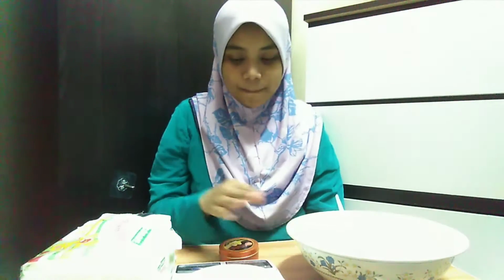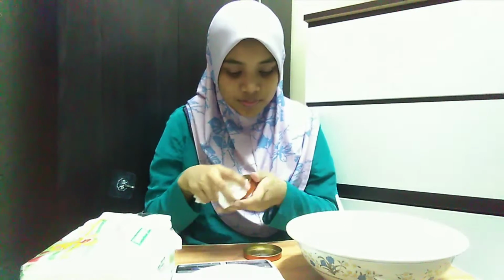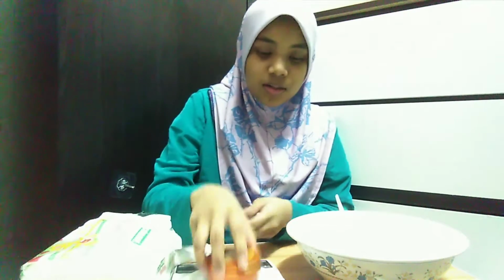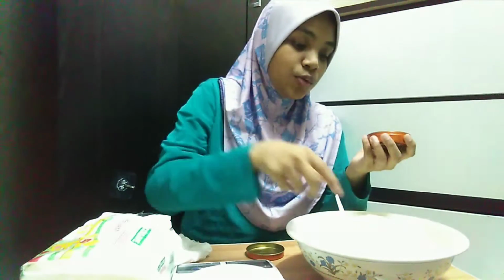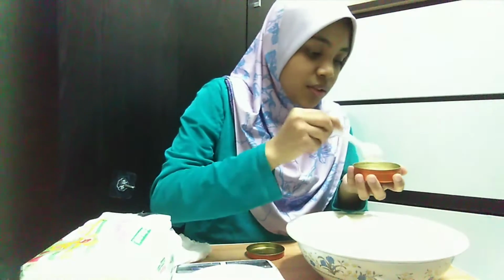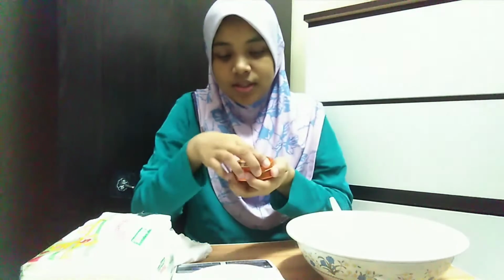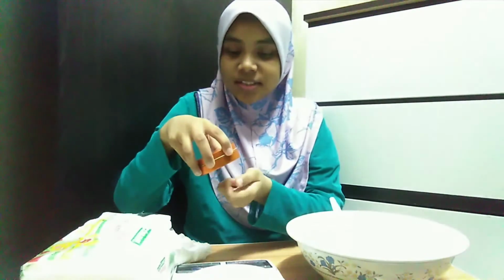For the moisture content experiment, we need a soil sample, balance, moisture can and its lid. Firstly, we must make sure that the moisture can and its lid are clean, so we wipe them with tissue. And we take the mass of the moisture can and its lid. Next, we use around 10 to 20 gram soil sample and we take the mass of the moisture can, lid and soil sample.